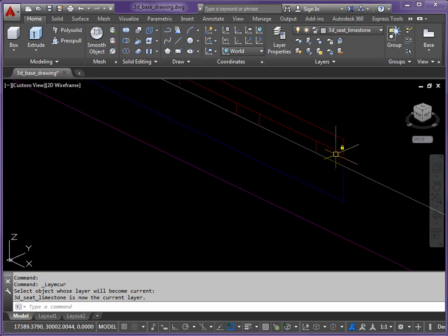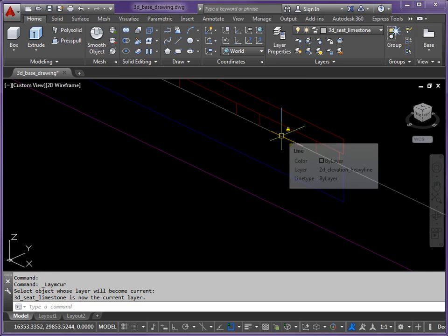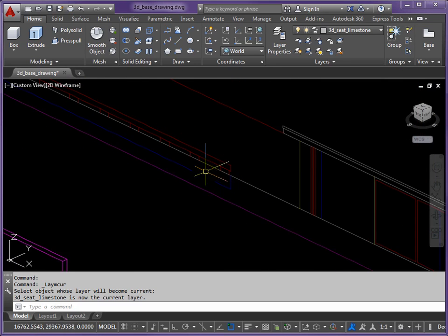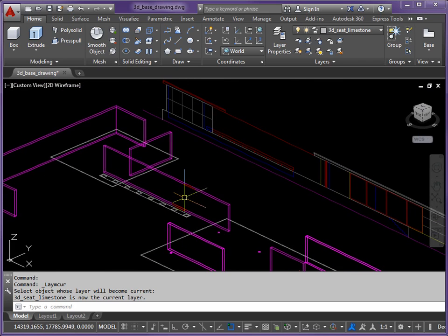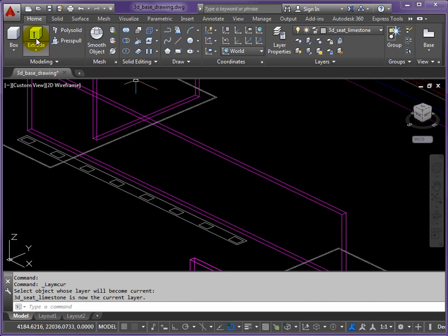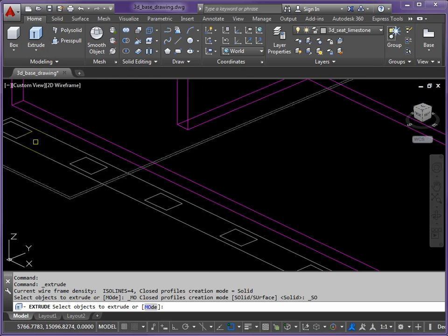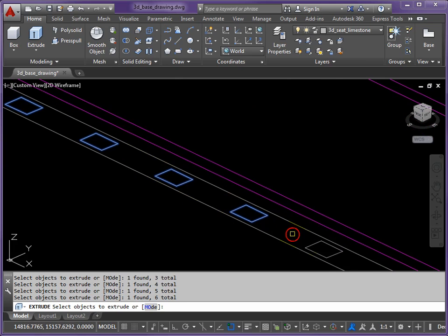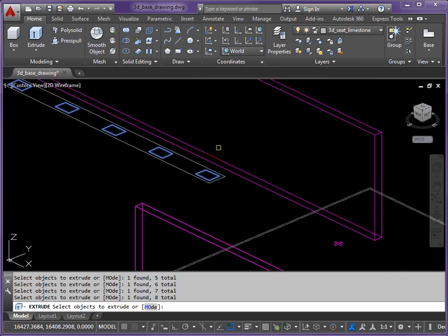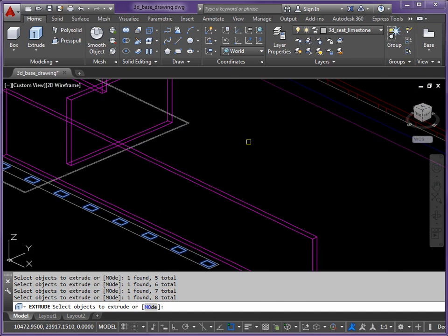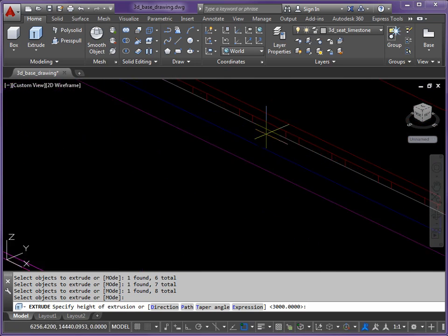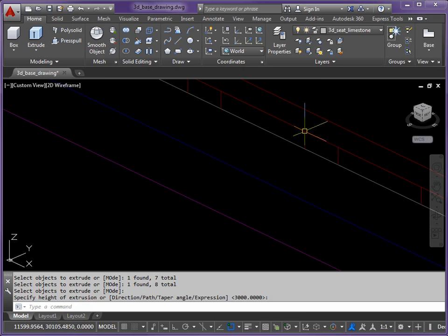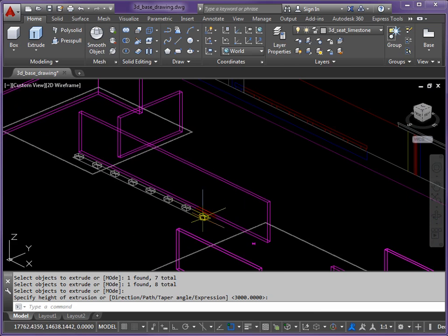Okay, and we'll follow the model, the drawing here. The seat is actually a bit thinner on top, but we'll use the 2D drawing for consistency. Okay, so firstly we want to extrude the boxes. Let's take all these boxes. So these are little stumpy kind of legs for the chair. Press enter, and we can take the height from the 2D information. So it just reads the Z information from this particular point. Okay, got lots of little boxes.